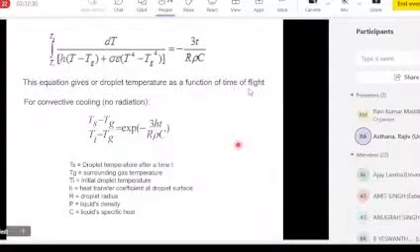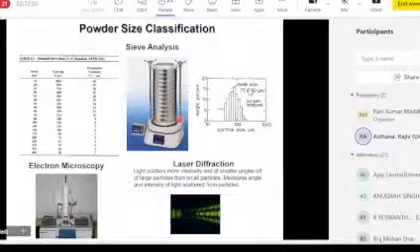So if you want fully solid, spherical particles, then you want the droplet to reach its solidification temperature and release latent heat during flight, so that once the droplet hits the collection surface, you get solid powders. So this kind of thermal considerations are used to design the thermal processes in atomization.